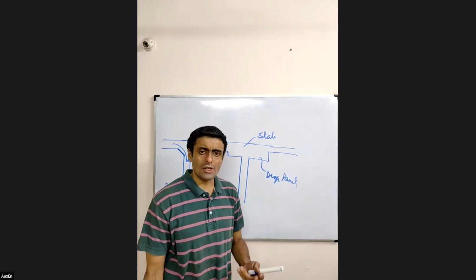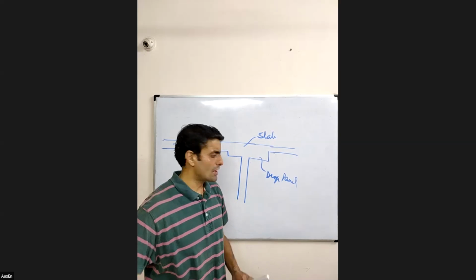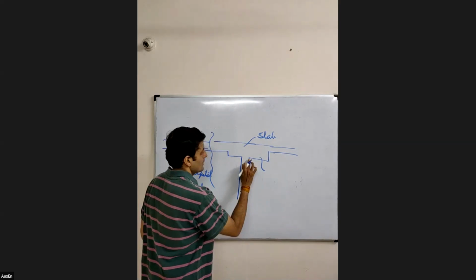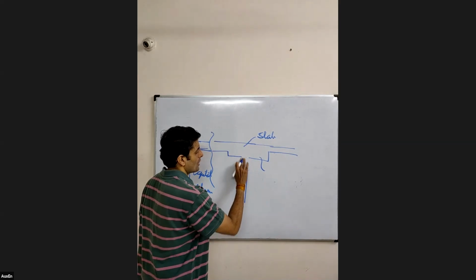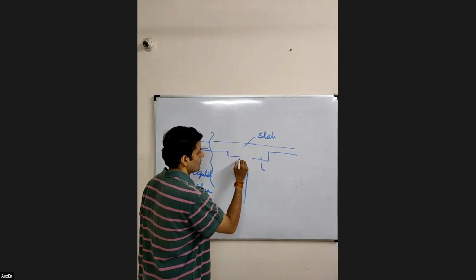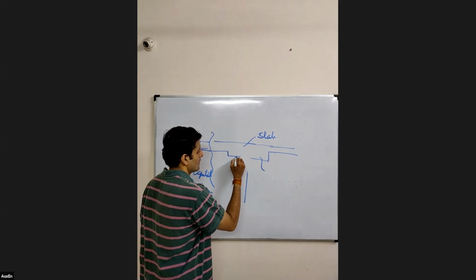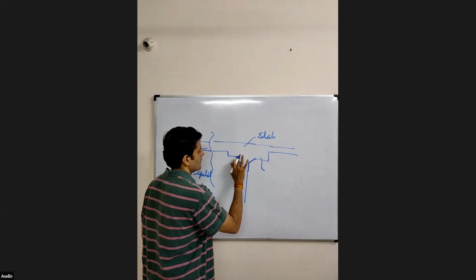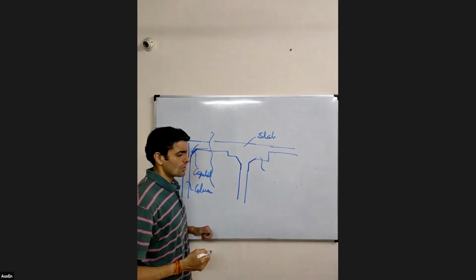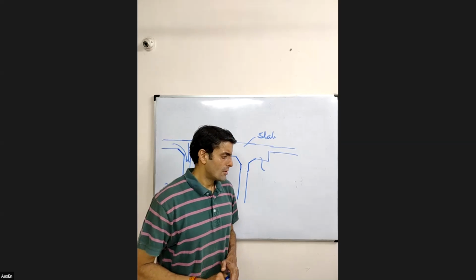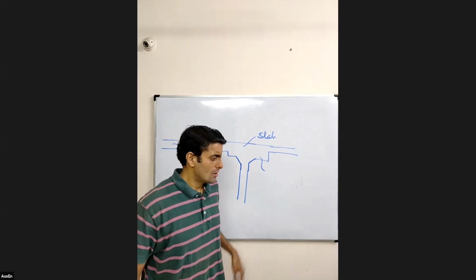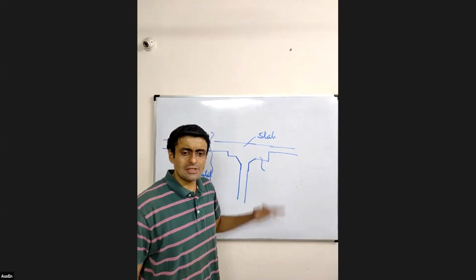Both. Yes, both can obviously be the third strategy where we are providing column drop also, sorry, slab drop also and column capital also. So you will find some places where you have column capital also provided and you have drop panels also provided. Okay, so yes, there are some places where you see both column capitals and slab drops.